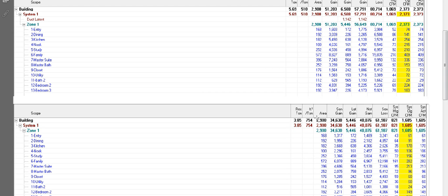And if you look at the square footage per ton, I promise you that when you start looking at a house that's 754 square feet, we are performing better than some Energy Star homes being built right now in the Dallas-Fort Worth area, and some LEED homes being built in the Dallas-Fort Worth area. The simple reason, first of all, is you could have an Energy Star home with the duct outside the conditioned space.